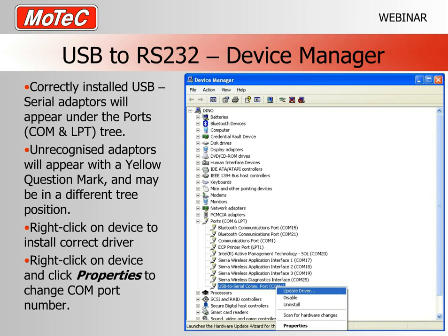In this case, you need to have the location of your driver files handy, whether you downloaded them or got them off the disk that came with our A10 device, and you must point the update driver process to those drivers, and you should be out of trouble. When that happens properly, you will then see this listed here, USB to serial COM port.